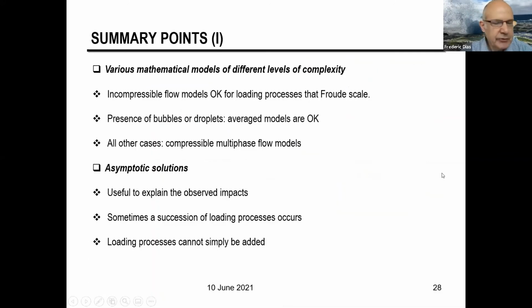So just to summarize, for the slamming problem, there are various mathematical models of different levels of complexity. The incompressible flow models are okay for loading processes that are flood scale. If you have bubbles or droplets, averaged models are okay. In all the other cases, compressible multi-phase flow models are needed. We have asymptotic solutions. They are useful to explain the observed impacts. Sometimes a succession of loading processes occurs, and the loading processes cannot be simply added.